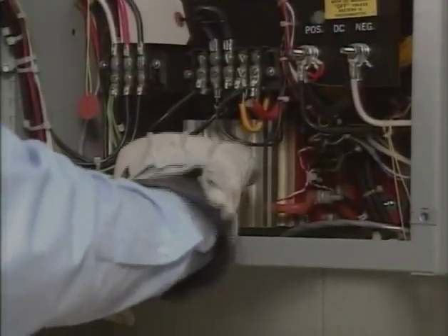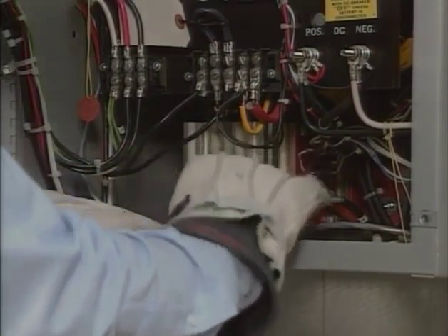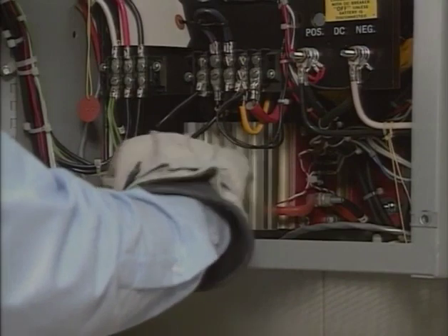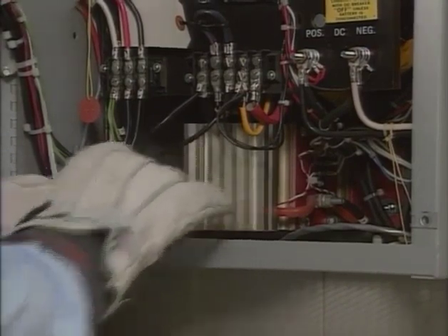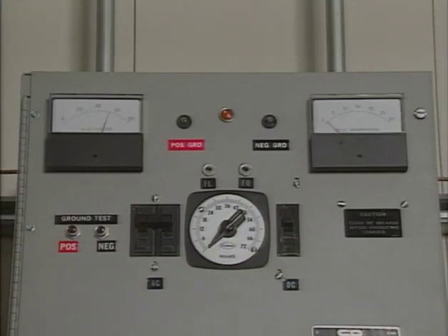A common cause of heat is dust buildup on surfaces designed to dissipate heat. Dust should be removed regularly. The internal components may be brushed, vacuumed, or blown clean. In addition to inspection and cleaning, the charger output voltage and current are noted and recorded. Any variation from the normal operating ranges should also be noted.